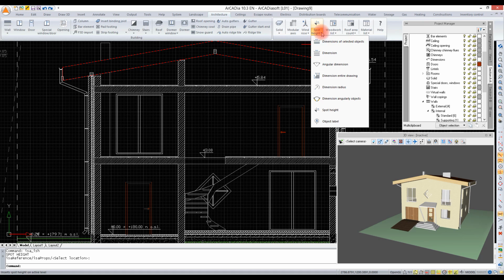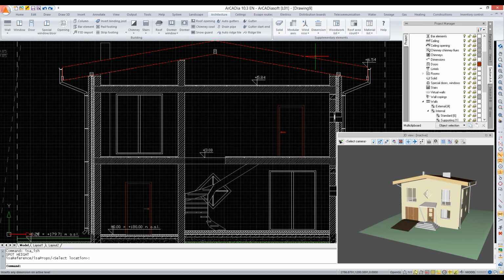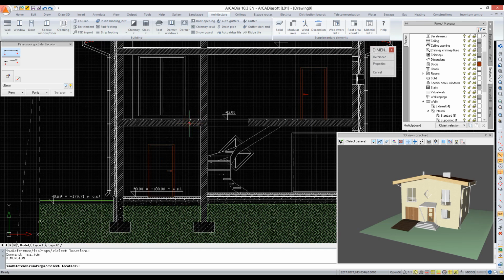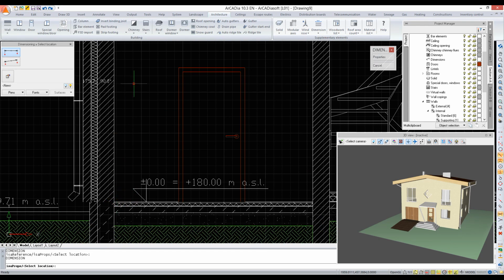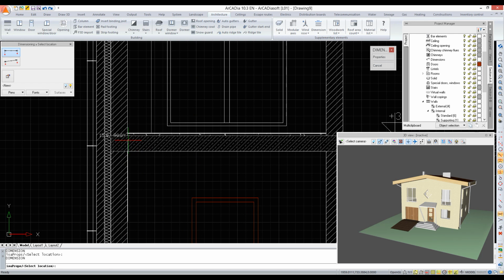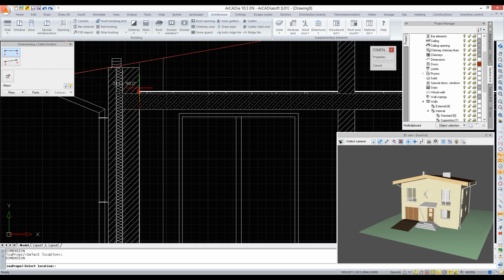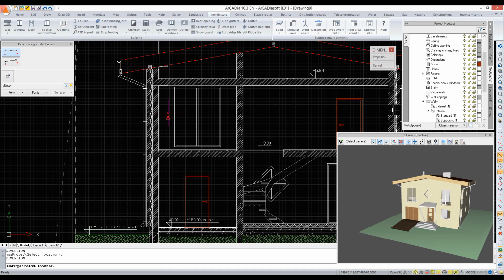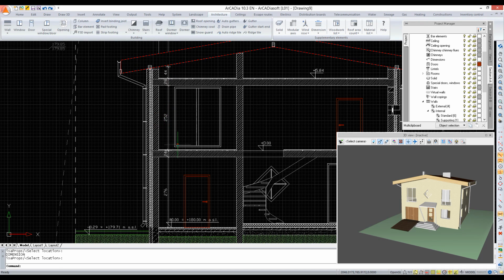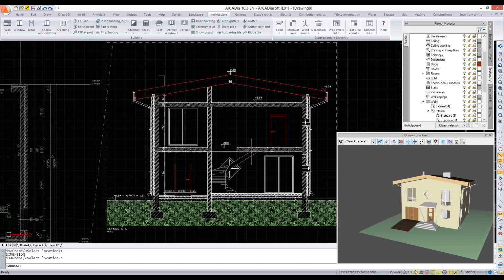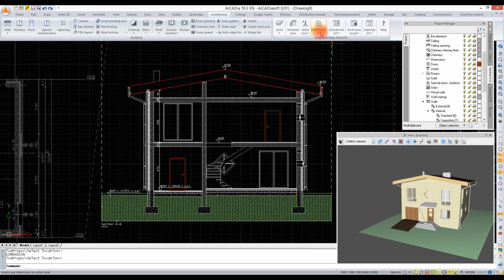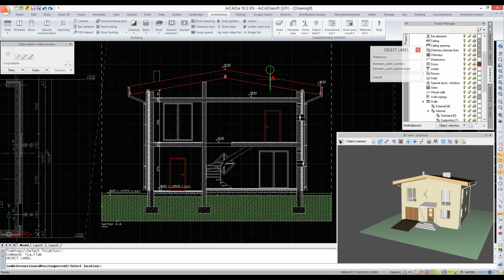When it comes to dimensions, we dimension here with free dimensioning, so we show the next points to be dimensioned. With the right mouse button, we confirm the entering of the dimension, and we show where this dimension should be traced. Now, on the cross-section, you can enter the object labeling of the elements. That is, the set of materials used in the given element.